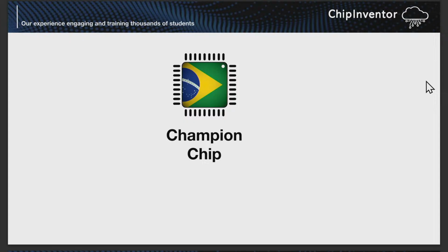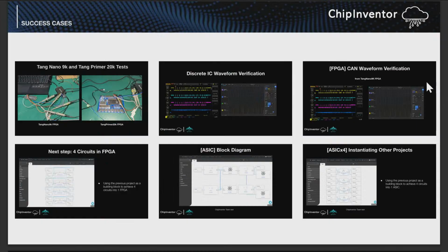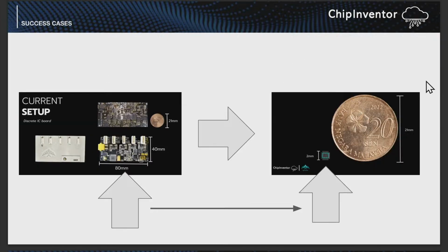They started using the block design approach, and they designed a CAN bus controller as a block, but they needed 8 of these blocks. Then they copied them as blocks, and they were able to test this on the FPGA. I was quick there, but there were some test results here.